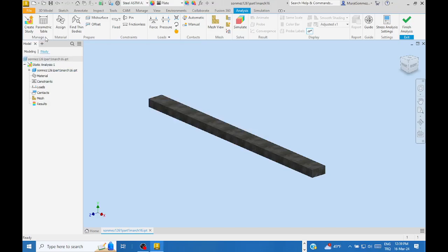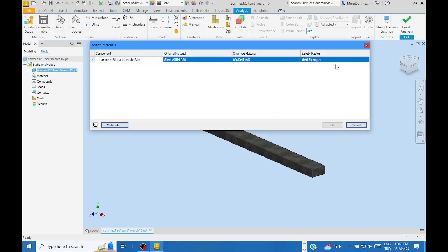One more thing. In performing the analysis, what is the threshold value? Yield strength or tensile limit? Yield limit. In most cases, yield limit. If this limit is exceeded, then find a solution either to prevent the yielding, of course, either change the geometry of the object if it is allowed by the customer, or again, if it is allowed by the customer, decrease the loads.